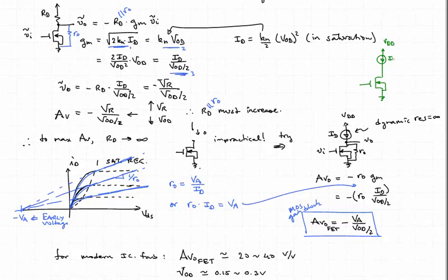So if you have a current source, and in order to bias this, what we could do is to add in this gate resistance, and let's make it really large. Let's say that you made it 1 mega ohm. Okay, and so what you'd have is that this voltage here, VD, the operating point, is going to be equal to VGS because of how this is tied together, right?